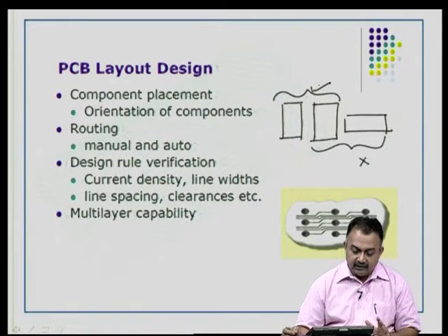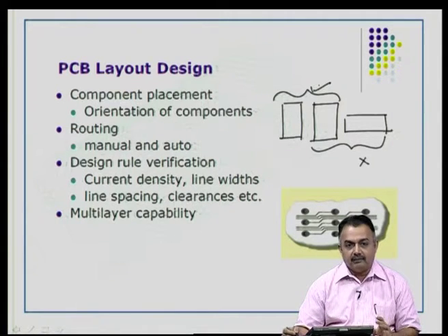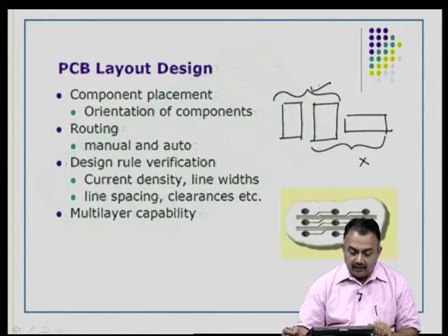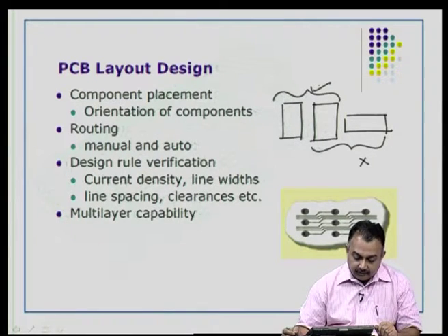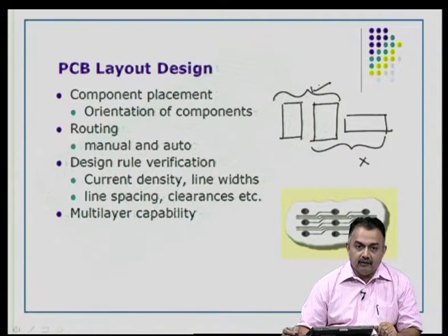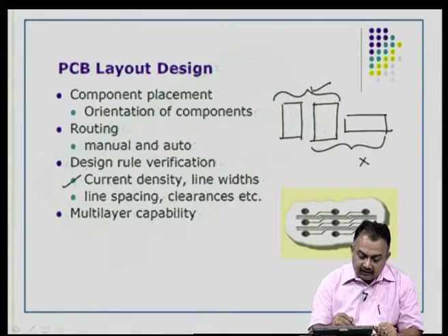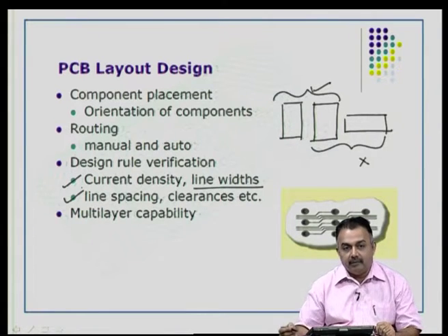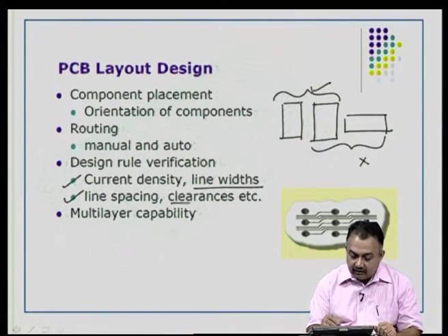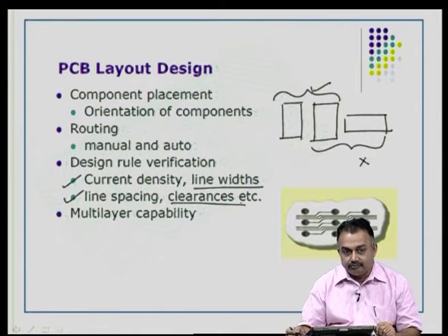various aspects in placement, then comes routing, that is manual and auto routing of the interconnects that you have specified in the schematic capture. Then you can do a design rule check or a design rule verification, basically to look at current density, the line widths that you require for manufacturing, line spacing that is specified by the manufacturer, clearances and so on.